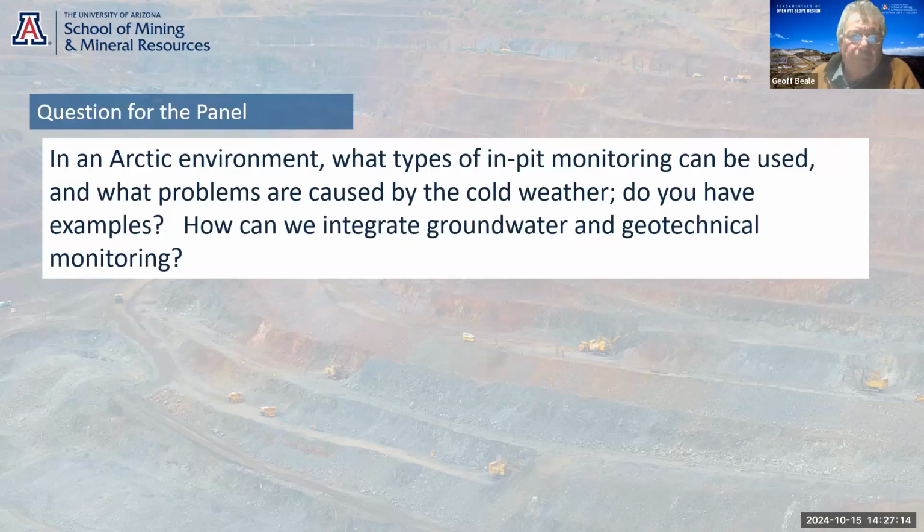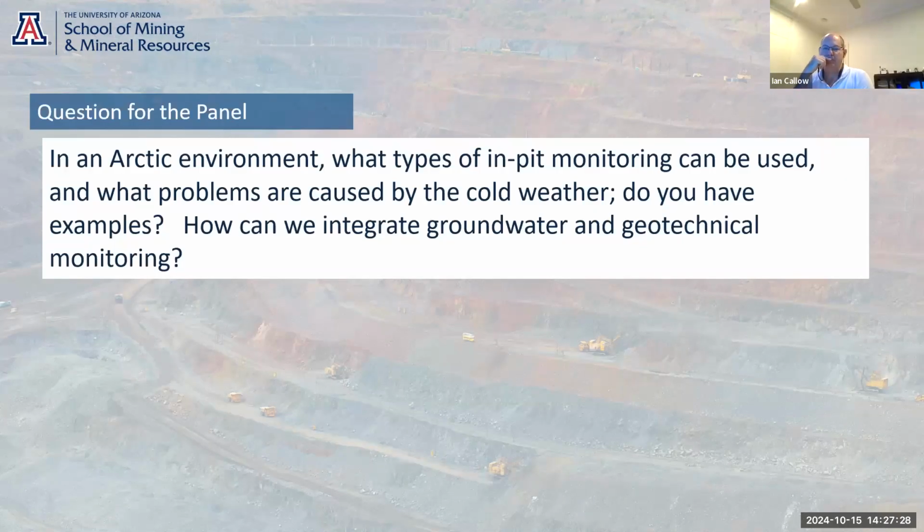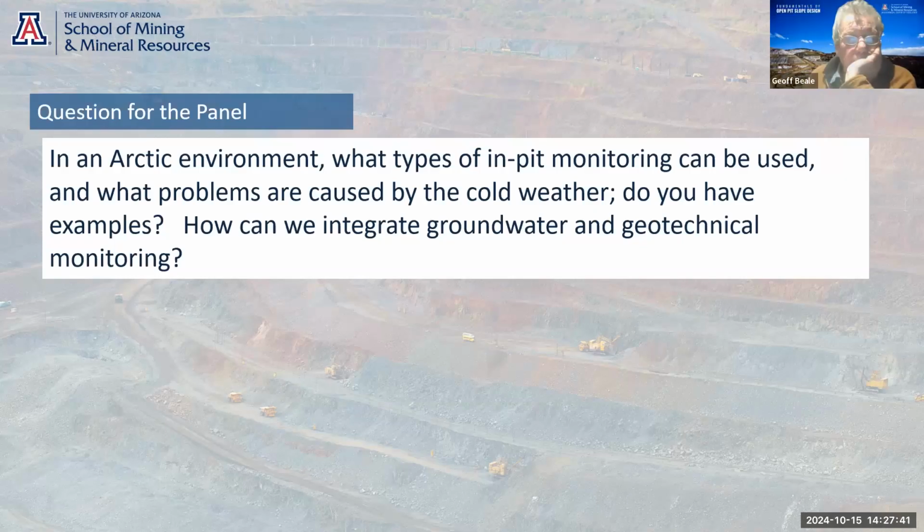So, yeah, VWPs and grouted in geotechnical instruments. Yeah. There is a problem with battery life in the cold. That's so true. You certainly need to be aware of that. Maybe there are better battery technologies around that I'm aware of. But at Diavik, which is very much in the Arctic, we struggle with battery life on instrumentation. And also with the solar panels you've got on your telemetry, you've really got to be careful of low light. Yeah, Diavik has lots and lots of vibrating wire piezometers all around the pits.